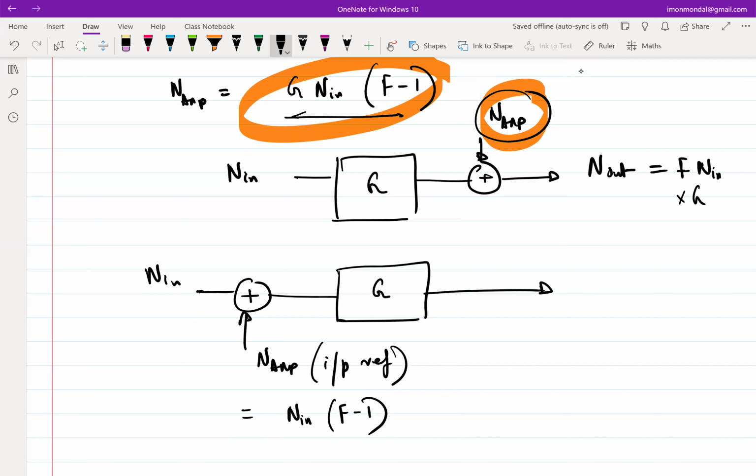It is standardized, right? So if the input noise is 4 kTr times 50, it makes sense to characterize everything with respect to the noise of a 50 ohm load. Then I do not have to back calculate this and that. And that standardizing with respect to the signal to noise ratio of an input or the noise contribution of the input is essentially what noise factor, or noise figure, does. So that's what we are doing.